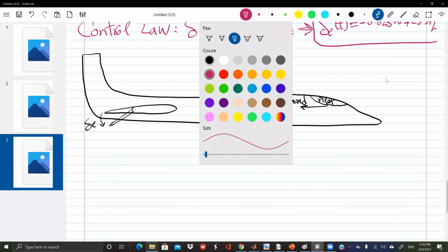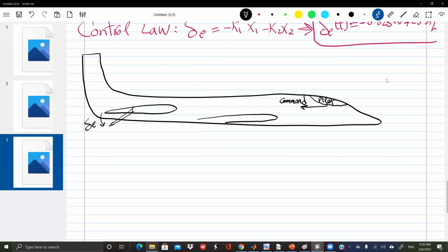So here is your wing. We're going to put some alpha vanes on the wing to get the angle of attack alpha. And now from the angle of attack alpha, you multiply by what to get W? Alpha multiplies what to get W? U0. So please put another sensor, a tube or something, to measure the airspeed. Finally, you have W.